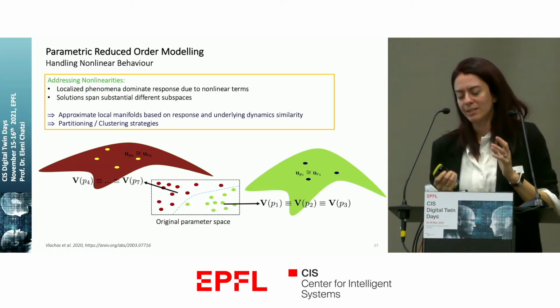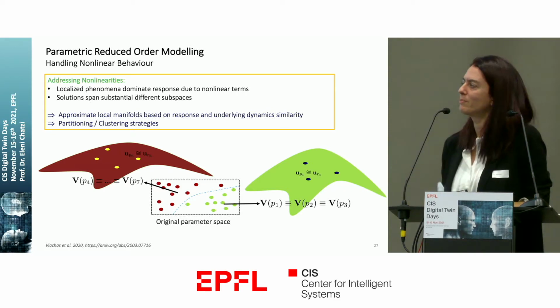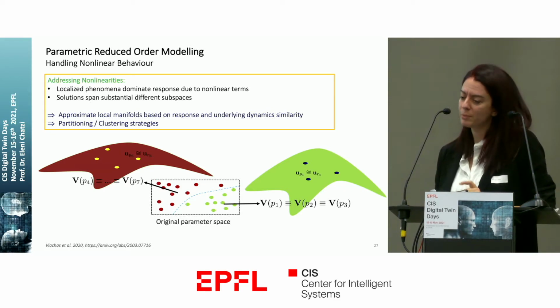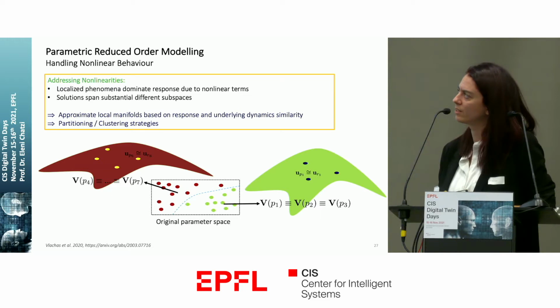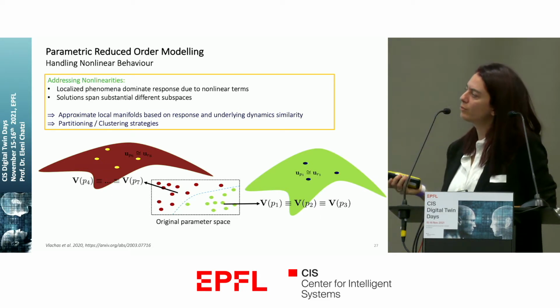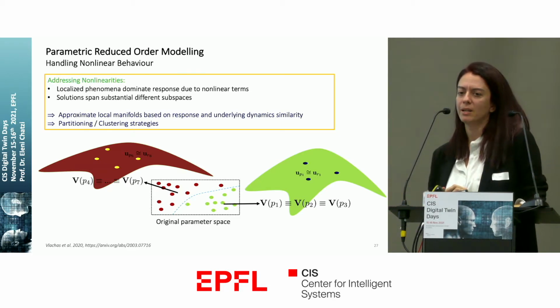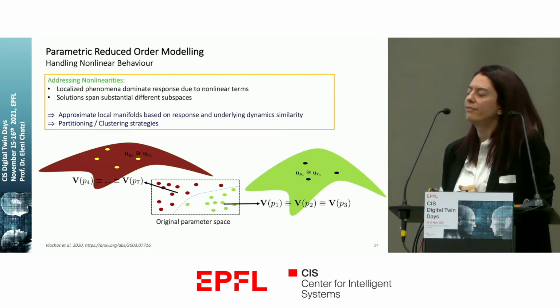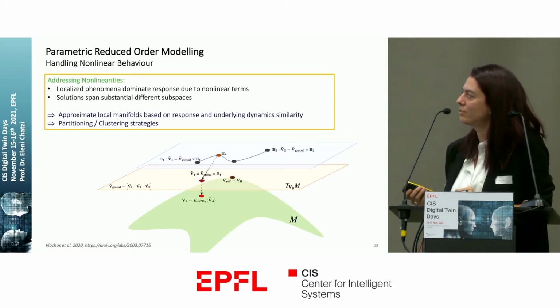Now, of course, because we discussed parametric dependence, this kind of a reduction has to be done over different sets of parameters. And for nonlinear problems, and particularly problems that could be non-smooth, for example, problems that involve fracture, that I will discuss next, this is non-trivial. It means that you have to efficiently separate your space of parameters, and you have to extract these Galerkin projection matrices in different clusters of the parameter space so that you can actually efficiently reduce your system. So you try to project this reduction in a manifold space.